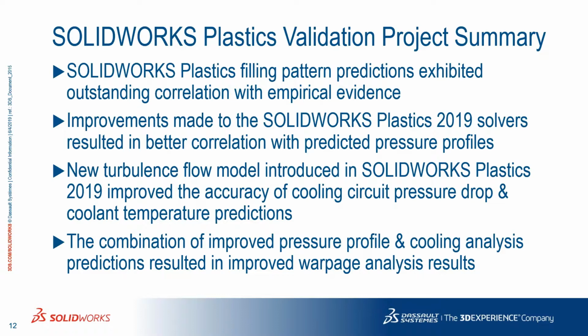But the most recent validation results tell us that the filling patterns that we predict have outstanding correlation with the empirical evidence that we see at the molding machines. We've already made improvements to the SolidWorks Plastics 2019 solvers to give you better correlation between simulation and real-world results. Part of those solver changes were a new turbulence flow model that we introduced in SolidWorks Plastics 2019 to improve the accuracy of our cooling circuit pressure drop and temperature predictions. That also leads to improved warpage analysis results. All of this stuff is connected.